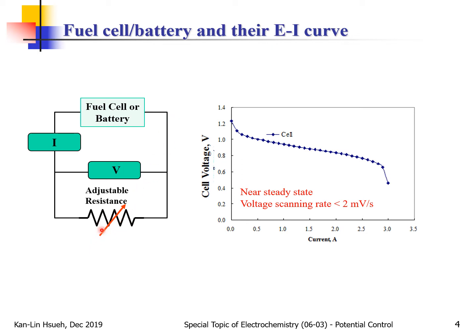We start from an infinitely large resistance and gradually reduce it. At infinite resistance, there is no current flow, and you get the voltage very high. As the resistance is gradually reduced, the voltage will gradually reduce. However, the current will increase. Eventually, we get this kind of polarization curve. In modern times, all this is done by machine automation, usually what we call an electronic load. They gradually adjust the equivalent resistance to make this measurement.